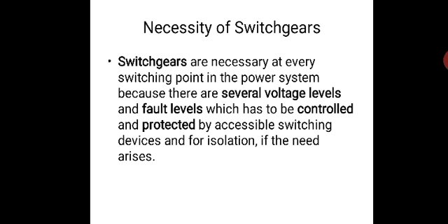See, what is switch gear and why is it important in a power system? Switch gears are necessary at every switching point in the power system because there are several voltage levels and fault levels which have to be controlled and protected by accessible switching devices, and for isolation if the need arises. Several voltage levels means high voltage levels up to kV levels, and fault levels means line to line fault, line to ground fault, etc.